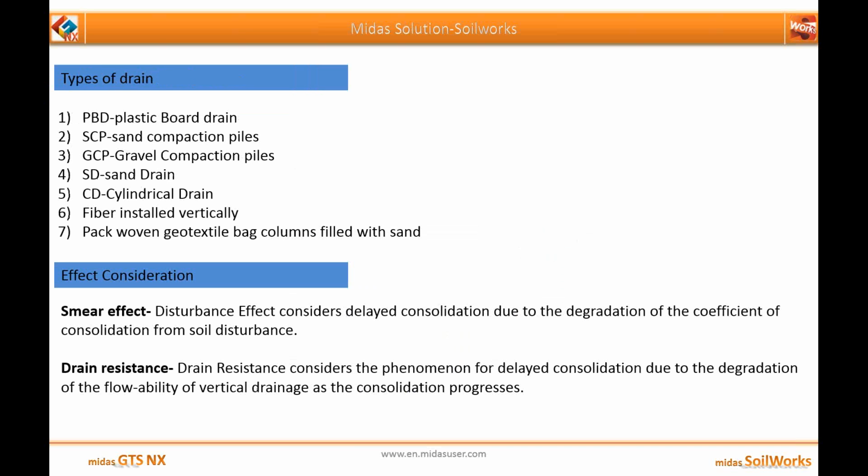Now, the type of drains which are available with Midas SoilWorks performing 1D consolidation analysis is PBD, that is the plastic board drain type; SCP, the sand compaction piles; GCP, gravel compaction piles; SD, that is the sand drain; CD, cylindrical drain; fiber installed vertically; and the packed woven geotextile bag columns filled with sand. Now, the effect which could be considered while considering this type of drain is smear effects. Smear effect is nothing but the disturbance effect.